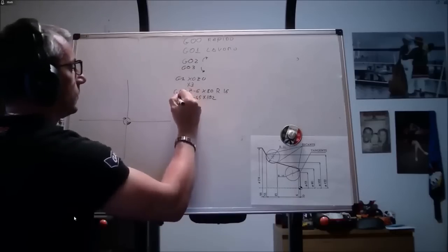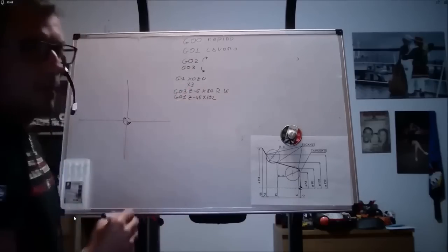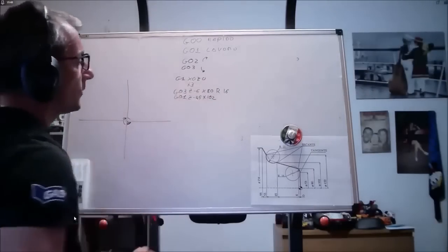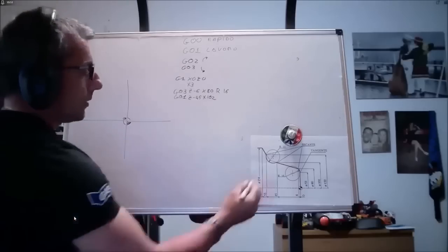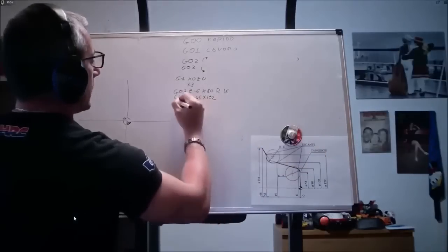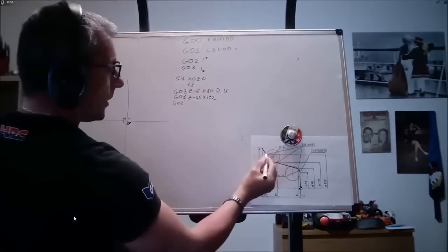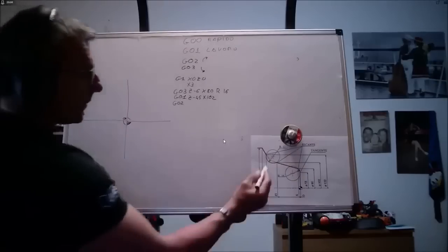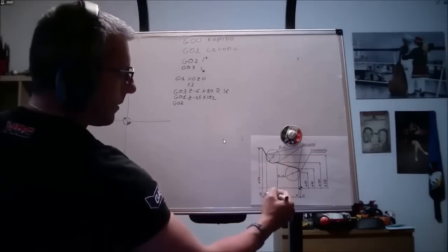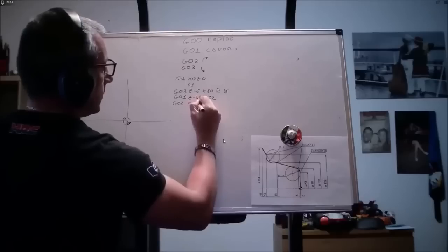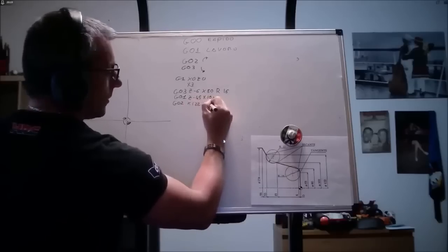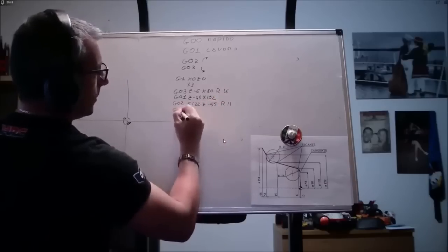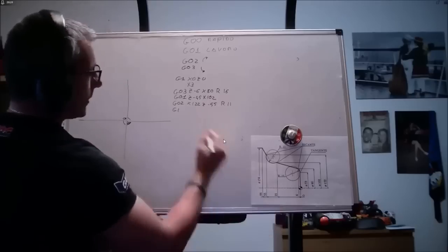We exclude G03 by inserting G01. If you see G3 or G1 written, don't worry. The 0 can be safely omitted. Here, as you can see, we have a G02 command in a clockwise direction that will end at X122, Z55, R11. Then G1 and two coordinates, X154, Z66.